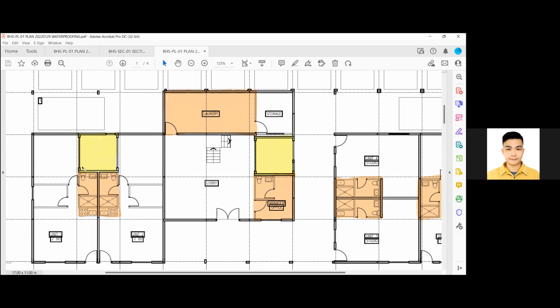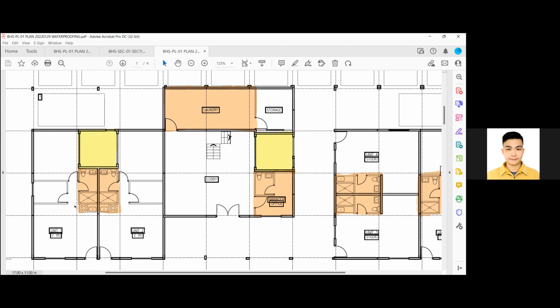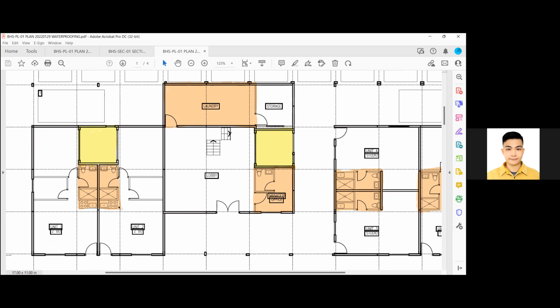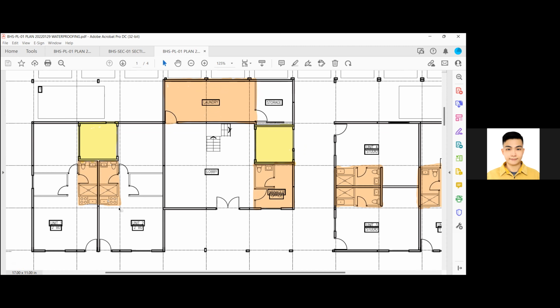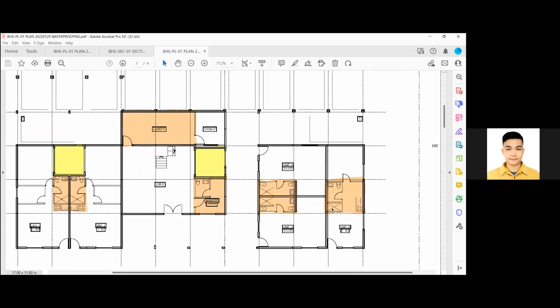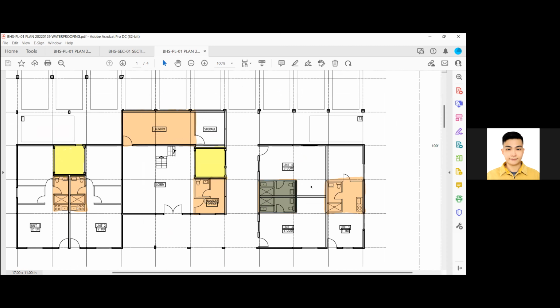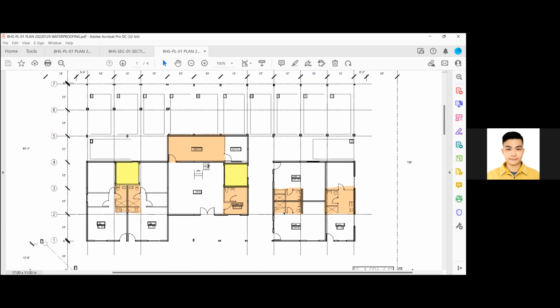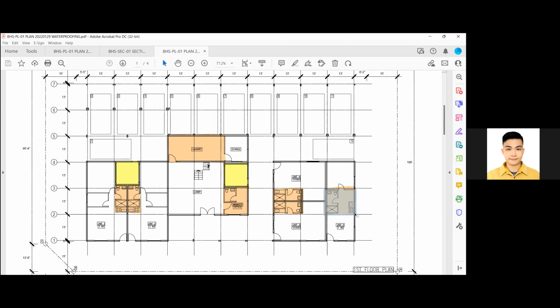So you may need to put specific additional waterproof layers, while these orange areas are the waterproofing layers that only apply to indoor areas. This one would be where the utility core goes, while this one is the manager office, and this one would be the laundry, because laundry involves a lot of water work, so it should cover the entire room.